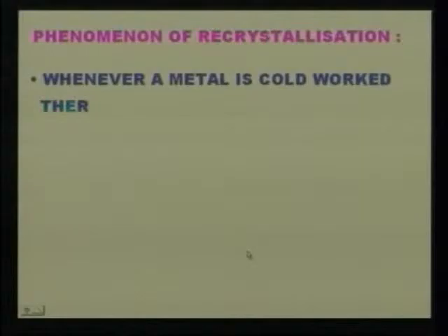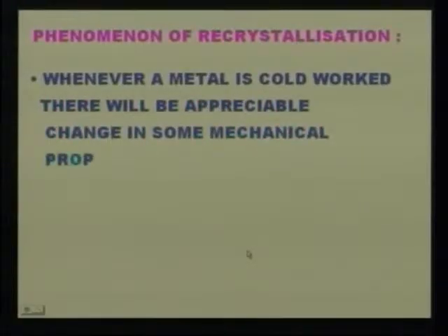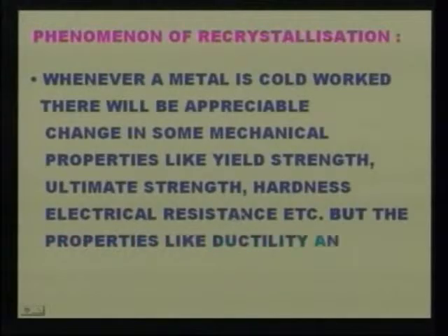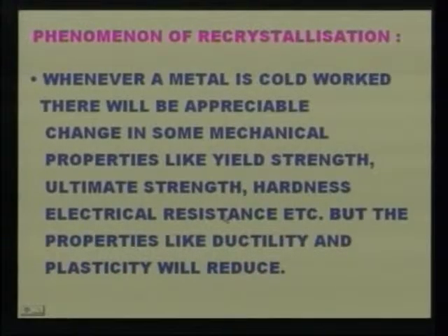Now let us know about the phenomenon of recrystallization. See, after solidification, there are some local strains and local stresses stuck between the crystals, which are disadvantages in applications. To improve the mechanical properties, you have to do the recrystallization process.